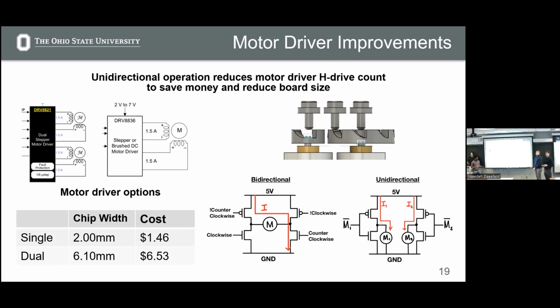And so after thinking about this, I realized that we could manipulate the way we connect the motors in our motor driver. And instead of connecting it between the two terminals to achieve current in both directions, we can just use current in a singular direction in order to power two motors from a singular stepper motor driver. And this greatly increases the benefit and value of using the single stepper motor because it's now sufficient for our design. It's much cheaper and it's much smaller than the other options we explored.